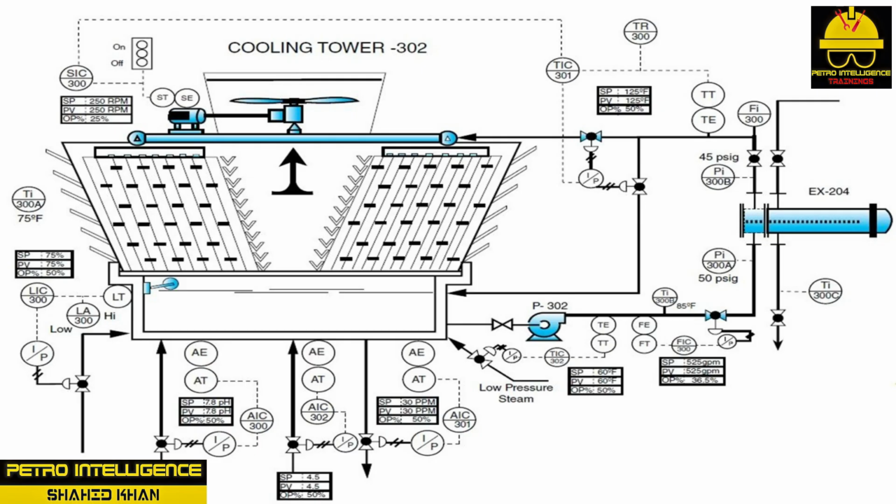As hot, moisture-rich vapor flows across the fill, it is lighter than the outside air and accelerates as it enters the plenum. This warm air increases in velocity as it is propelled high above the cooling tower by the fan.